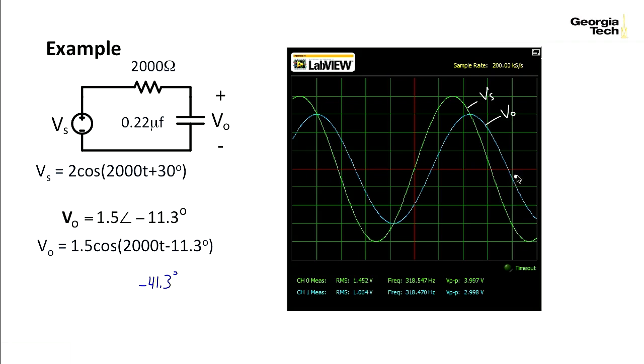And looking at this, this shows voltage peak to peak. That is twice the amplitude, 2 times the amplitude. And this again is 2 times the amplitude. This is the input, and this is the output amplitude, because remember, blue is the output signal. So the input amplitude was 2, and the peak to peak is 4, so this is at 2 right here.